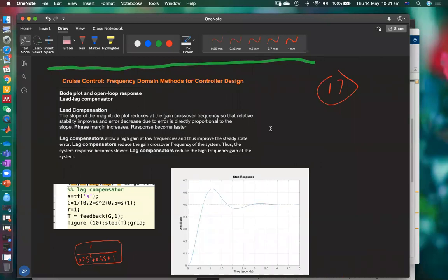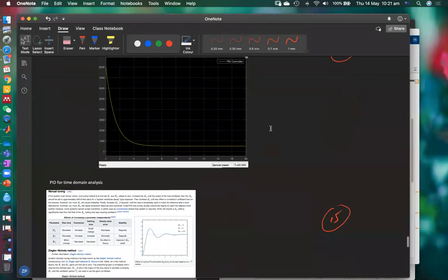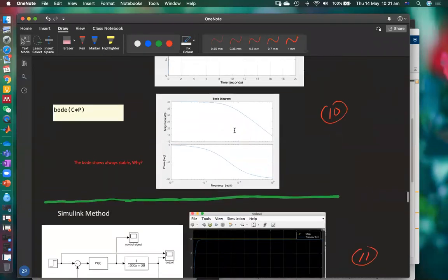If you have that phase margin, doing PID control is fine because after the PID control, you can still plot the Bode diagram over here. You can still check the phase margin. That's fine. You can do that. However, this is not a simple relationship. You can't easily get a relationship by changing the KP, KI, or KD to know what kind of phase margin you are getting.